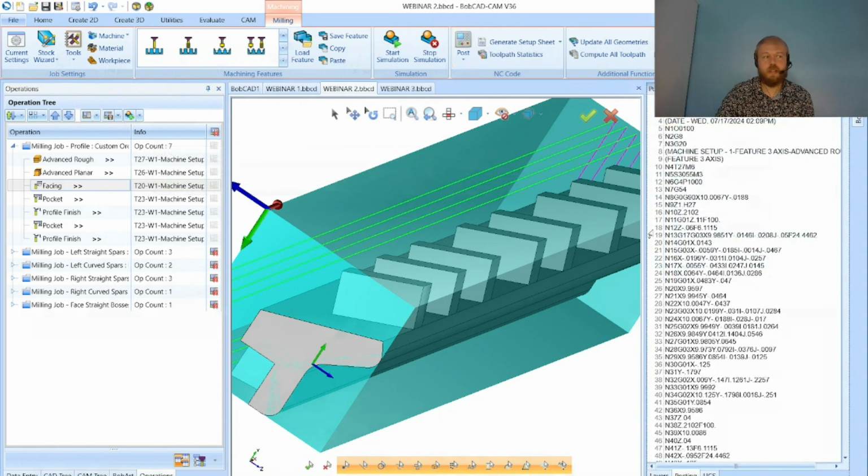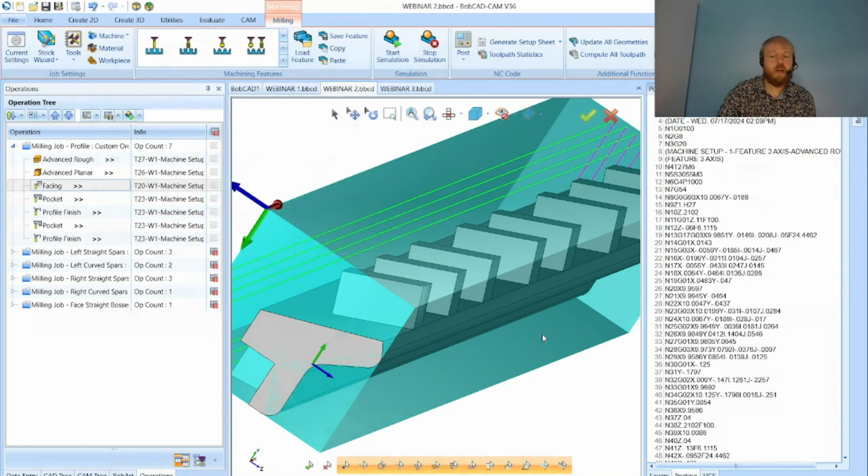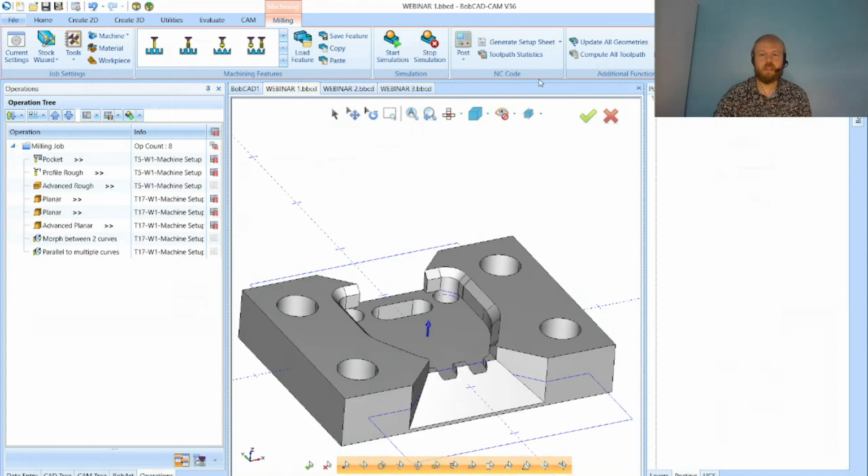It will generate the G-code here on the right-hand side, where I can right-click, save it, and save the NC file onto a flash drive to send it over to the controller from there. We also have RS-232 communication. So if you have an older machine, you can right-click on NC Editor, and we have a DNC option. So if you have a cable from your computer to the machine, you can set the port number and all of those settings to send or receive from a CNC machine.